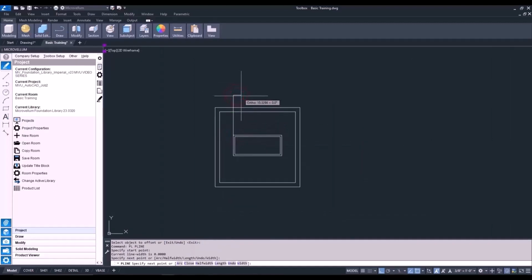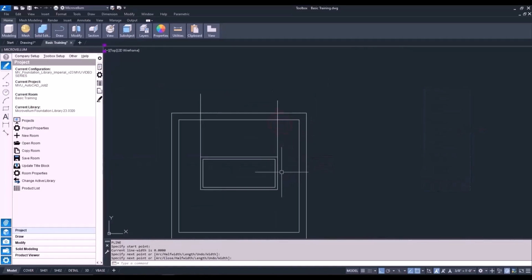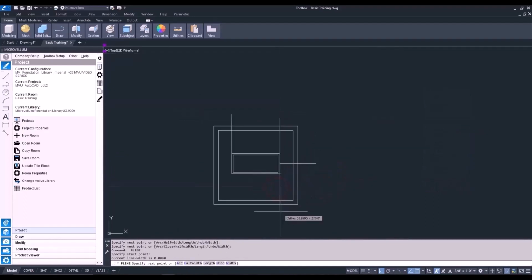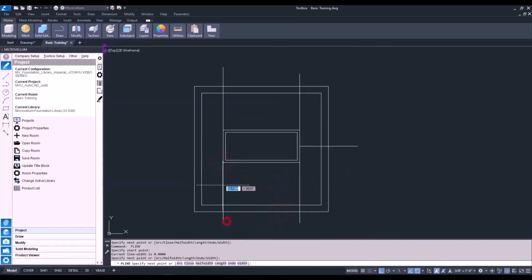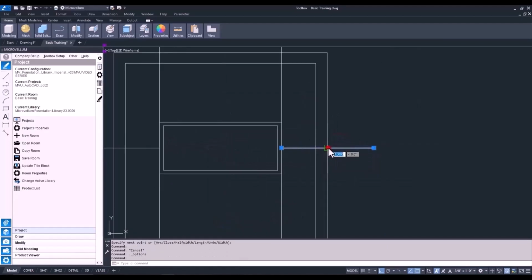And the polyline doesn't have to be a specific length, it just needs to go through that outer polyline. Just continue going around the drawing, some of those polylines at endpoints and the 2 horizontals at the midpoint. Now we're almost ready to trim, but we got to move those horizontal polylines. Now you can do this the slow way by selecting one object at a time and grabbing the center grip point and moving it with your mouse, but that's not very efficient.